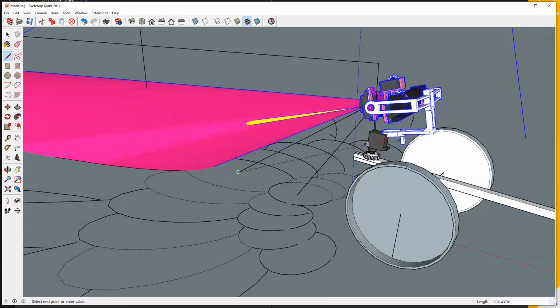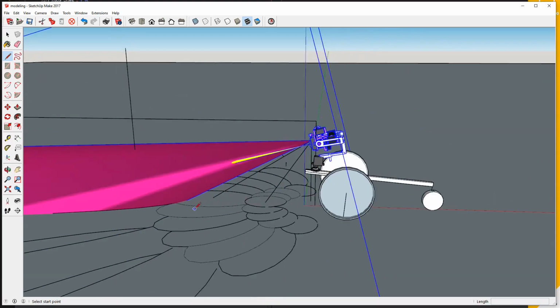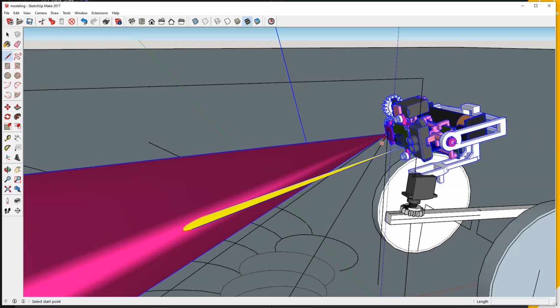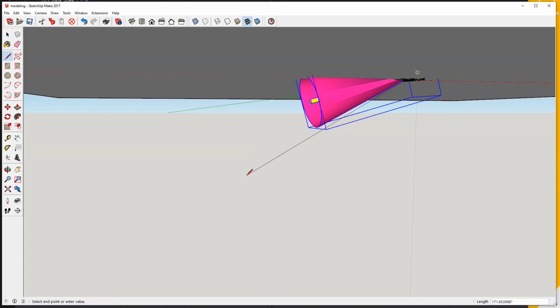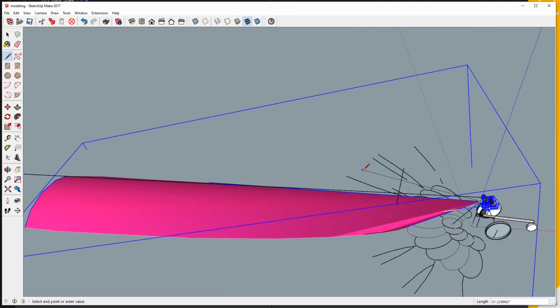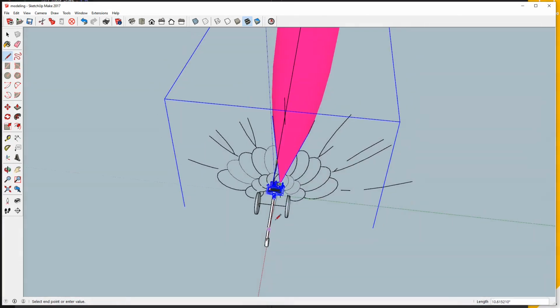So we're gonna have a bunch of those rays, and if those are all saying it's a flat floor, it's a flat floor. If, for example, it's a ledge, then they'll shoot through the floor. It's gonna say like 170 or whatever, some crazy number. It's like, alright, I should not go that direction. That's how this part of the mapping works.